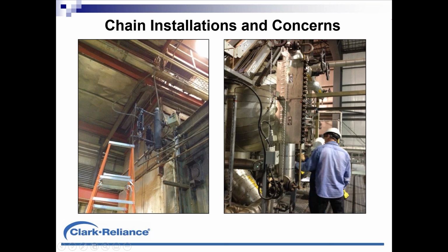The thing here, you can appreciate there's no way that he could reach this upper valve without a chain. The problem with this installation, however, is they've got that chain like a bicycle chain between those two chain wheels, and I can almost assure them they will not get tight shutoff on both valves. Can't tell you which one, but either the water or the steam valve will shut tight when that chain's pulled, but very likely not both.